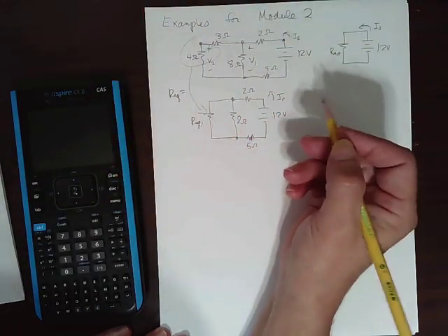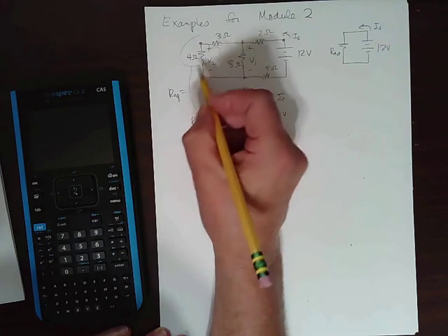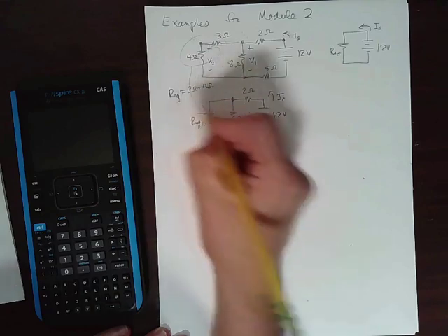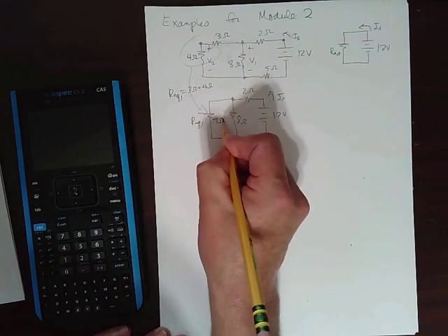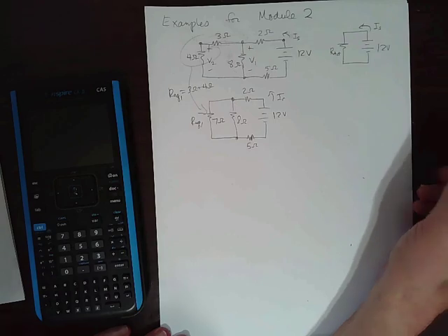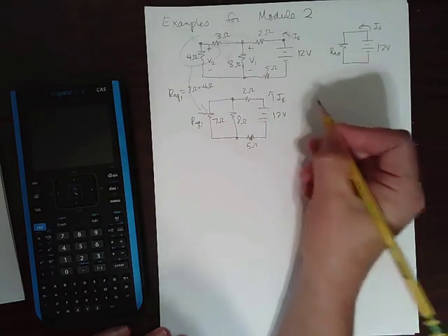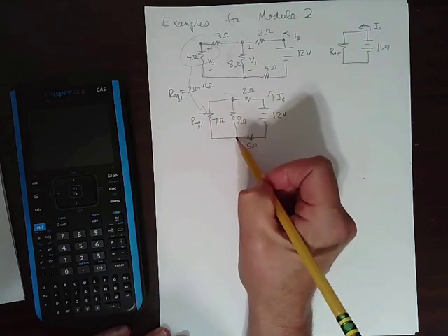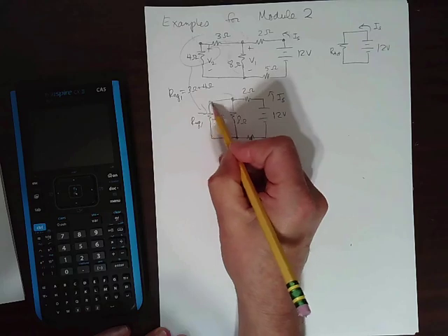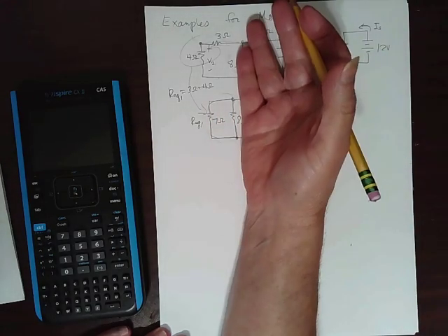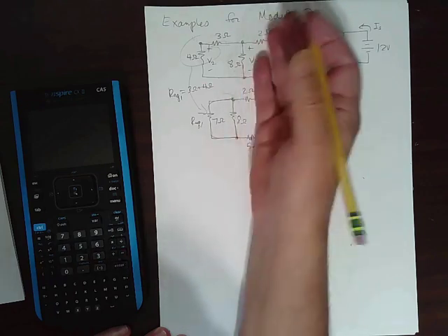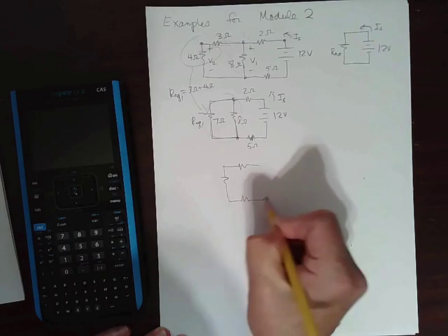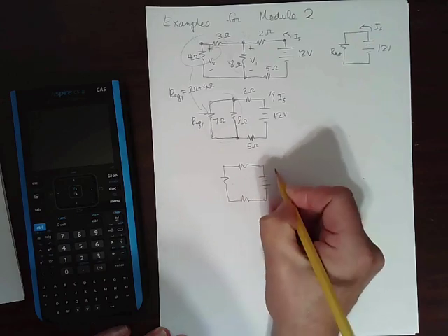All right, so for that to happen, we know that resistors in series add, right? So it's going to just be 3 ohms plus 4 ohms. All right, so R equivalent 1 has to be just 7 ohms. All right, and the rest of the circuit will not know the difference. Now, like I said, once those two are combined in series, now these two are in parallel, right? Both the lower ends are touching and the upper ends of both of them are touching each other, right? So these two, the 7 and the 8 ohm resistors are in parallel with each other, so we can mush them into one resistor. All right, and then the rest of the circuit doesn't know the difference.